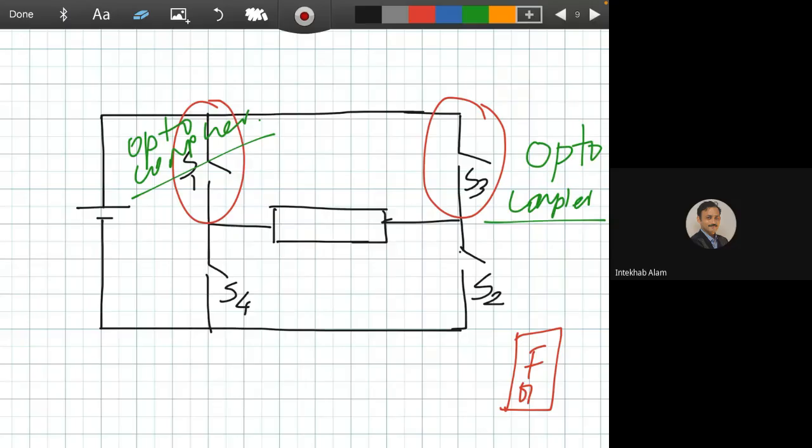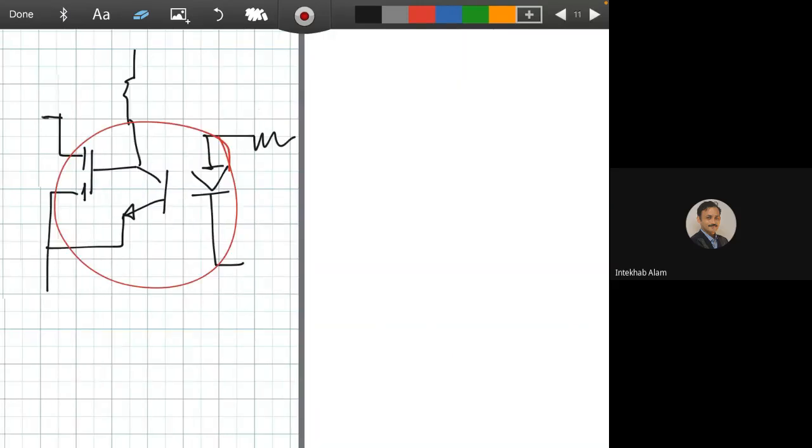In the full bridge circuit, we have only one voltage source compared to the half bridge circuit. And there is no transformer, so the loss is very little. Since there is no transformer in the half bridge and full bridge circuits, we can make them very small compared to the push-pull one. Only the switching loss is here. In all circuits we have some switching losses. So if we figure out the switching loss for all circuits, what will happen?